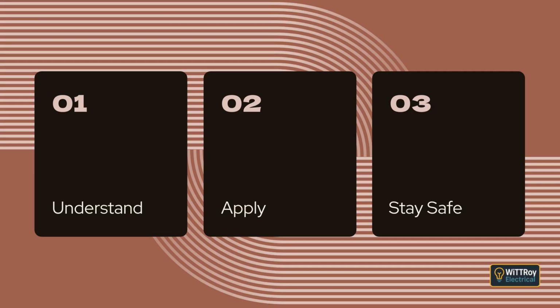Clause 3.3.2.7 Vibration. Wiring that is exposed to vibration must be suitable for it. Any vibration strong enough to damage cables, fixings, or connections means the entire wiring system must be able to withstand constant movement without failing. Everything must stay secure and reliable under those conditions.